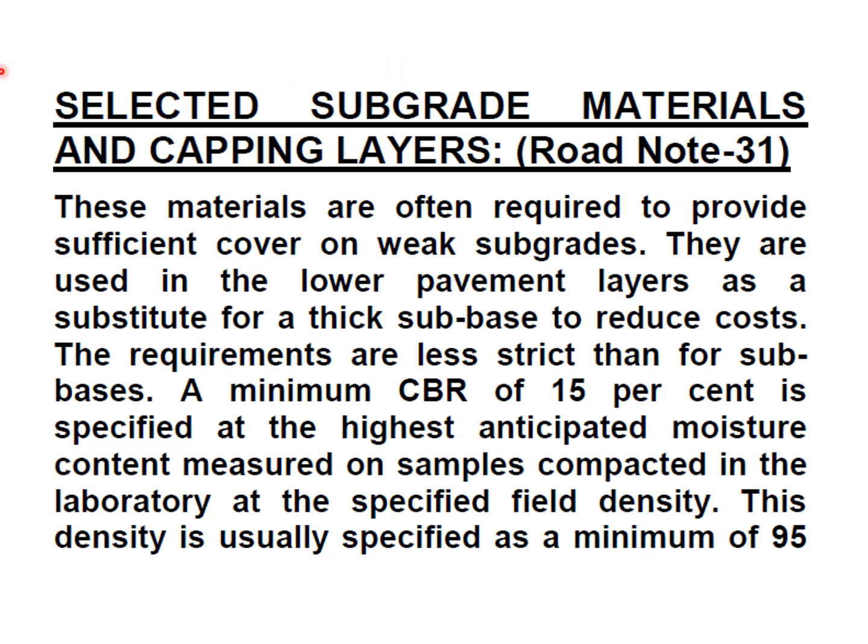So the title is Selected Subgrade Materials and Capping Layers as per Road Note 31. These materials are often required to provide sufficient cover on weak subgrades. They are used in the lower pavement layers as a substitute for a thick subbase to reduce costs. The requirements are less strict than for subbases.